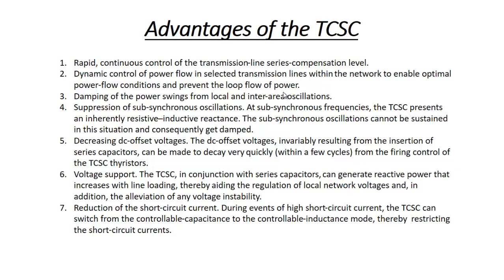Voltage support. The TCSC in conjunction with a series capacitor can generate reactive power that increases with the line loading. Definitely, because it depends upon the square of the current. As current increases, this reactive power also increases, thereby aiding the regulation of local network voltages. So we can say it will automatically take care of the voltage. And in addition, any voltage instability will also be prevented.